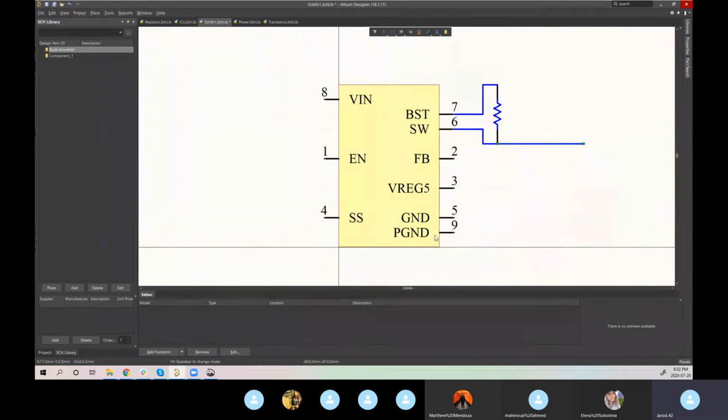Sometimes you can't avoid it, especially with large pin counts. If your package has a lot of pins, you can't use a full schematic for one part. So sometimes you have to make that compromise and bring in your pins tight together. But when you can, if you know your design, it's nice to space your pins so that your connections will be a little easier, a little cleaner. I am going to drop it down still, though, just because I think we can work with it.